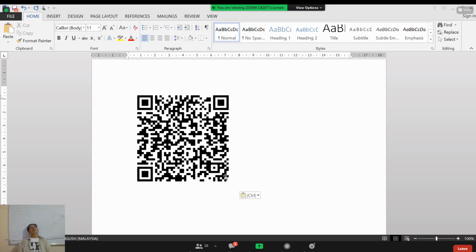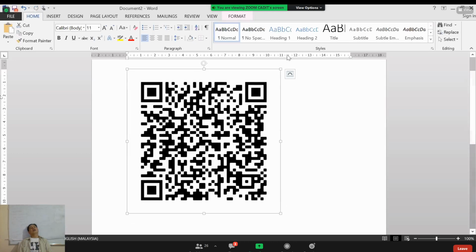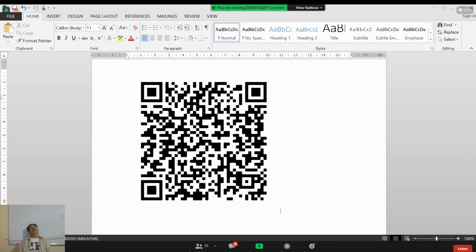Naveen, there is a question. Does this software work only for ICs or only PCBs? Basically, Sherlock is meant to analyze a printed circuit board assembly. That means we have a printed circuit board, and we also have components that are soldered on the board. So what we are doing is a study, let's say for vibration or mechanical shock.